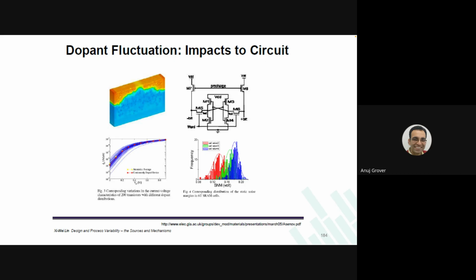And notice that when we said that 3 sigma variations would happen on my VT, we have kept the sigma variation to be 30 millivolts, something like that we had put. 3 sigma plus minus 90, and so this could be 80, and 3 sigma variation from this could be taking a device here, even faster than typical.